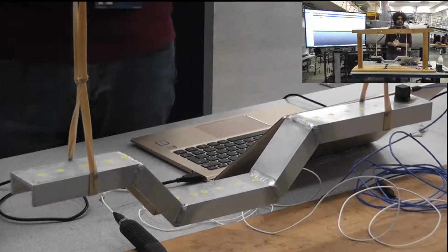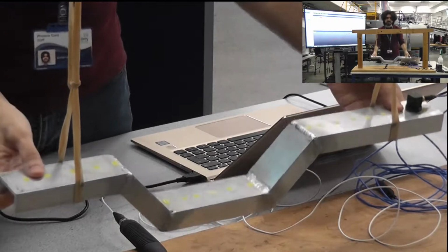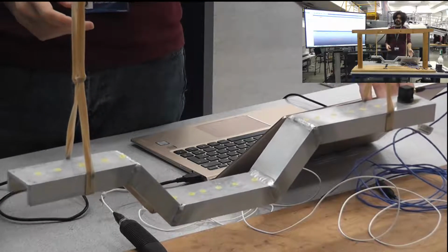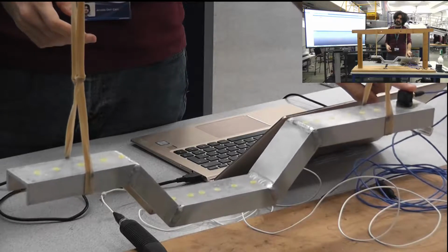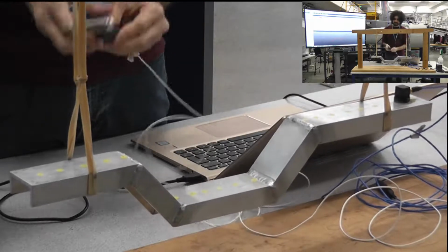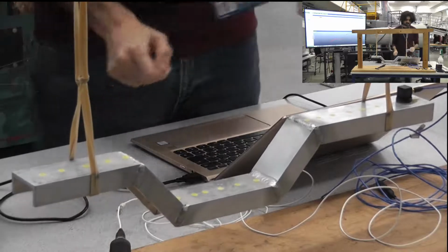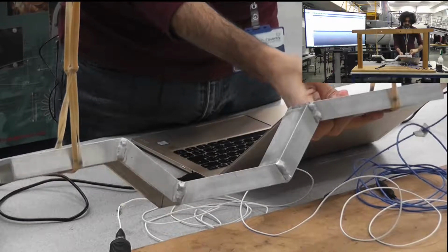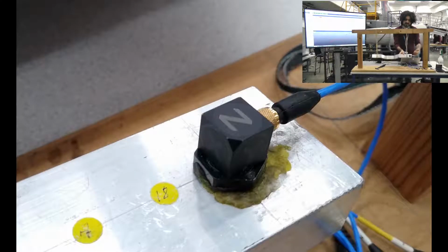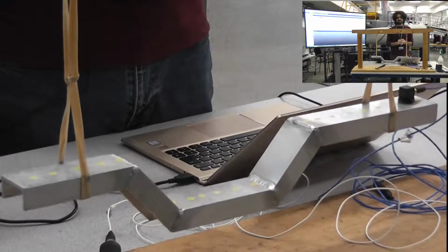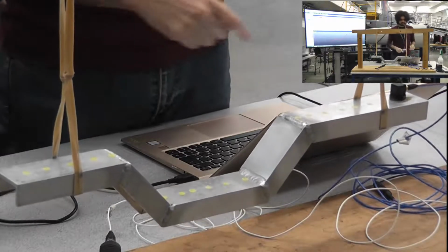Now I want to start showing the experiment. This is the structure we are going to study. This structure has been instrumented with an accelerometer here, and we also have a modal hammer here. The accelerometer itself is a triax accelerometer. If I can show you, there are labels here: there is a label Y, there is a label Z, and there is also a label X on the side. That means this accelerometer can record data from 3 different axes.